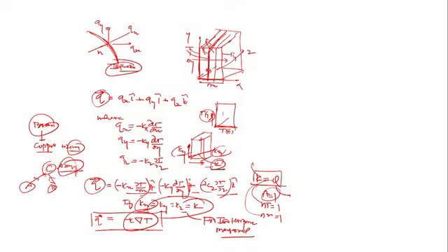The thermal conductivity of the alloy is much lower than the thermal conductivity of A and B. Means it is low. The thermal conductivity of the alloy is lower than the thermal conductivity of either of the pure constituent species. Clear, beta? Why is it so? Let's say this thermal conductivity is 50, and here it's 30, in watt per meter per kelvin. When I mix them together in some proportion to make the alloy, its thermal conductivity is less than 30. It's 20 here, less than either of the materials.